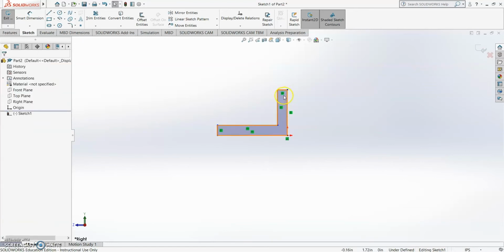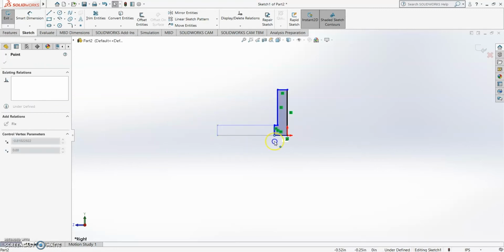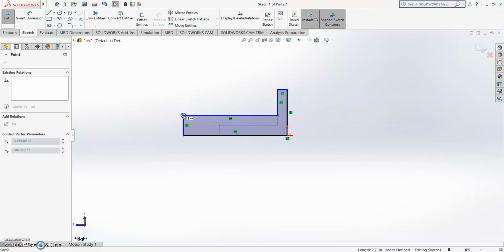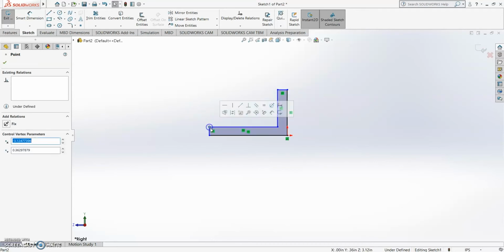And so you'll see here, all of my lines have these little green boxes. This says vertical, this says horizontal, and you'll also notice that whenever I hover over it, it highlights the line that it's referring to in pink. These are geometric constraints. So basically, no matter how much I move this point, this line will always stay horizontal. This line will always stay horizontal. Similarly, if I move this point, these lines will stay horizontal and vertical because they have those geometric constraints.